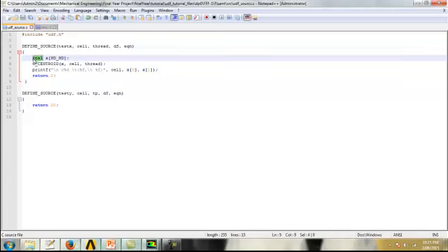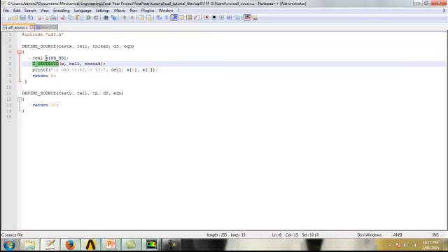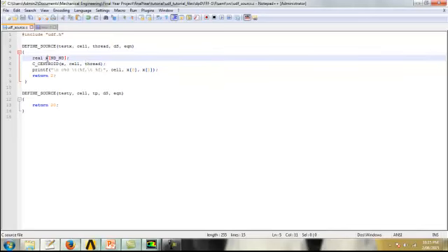Usually you define a vector, an array of real variables, and then you call this macro here, and that puts the x and the y location of the cell, if it's 2D, into this variable. If it's 3D, then the size of this will be 3. That's why you're also using this macro ND_ND, which probably stands for number of dimensions. I'm going to take a random guess at that.